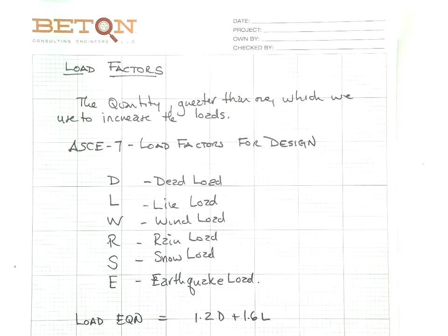A hospital might be 100 pounds dead load and 150 pounds of live load, which means that for a given structure, the hospital will be beefier than the school will be. And then residential might be 25 pounds dead load and 45 pounds live load. I can look it up in ASCE 7 if anyone wants to see what those are. I can find them for you.